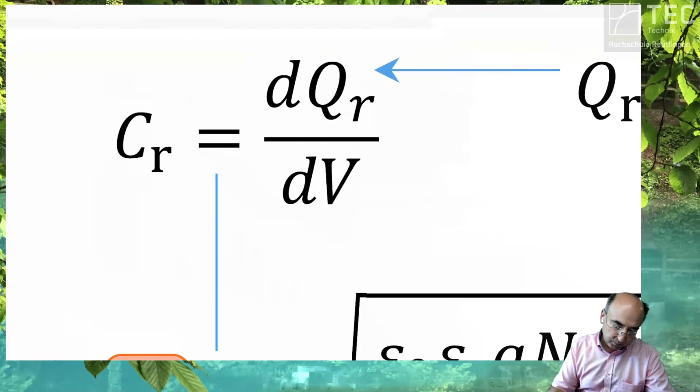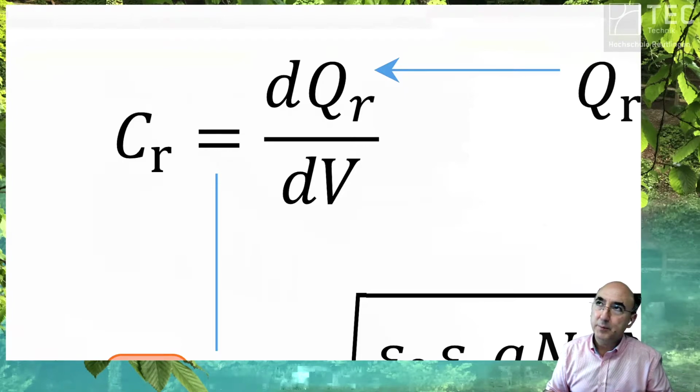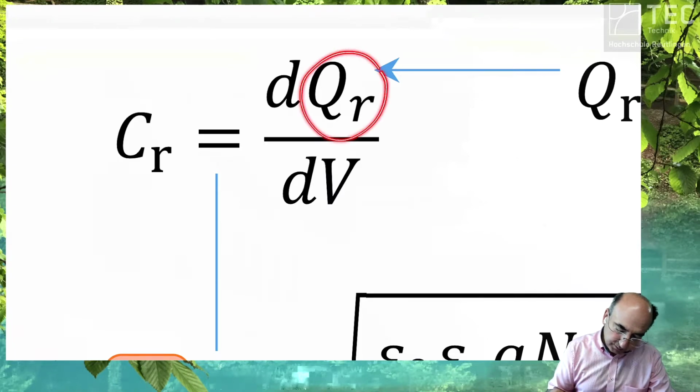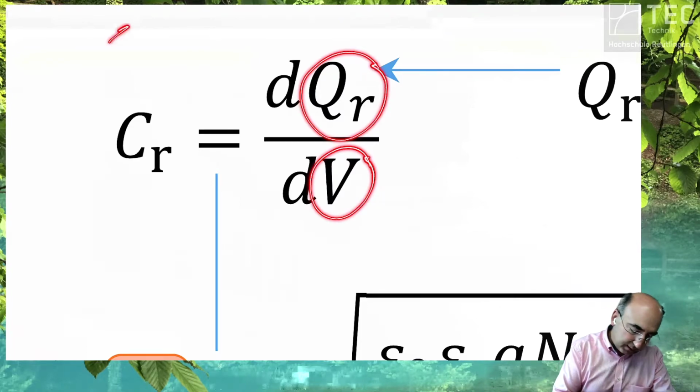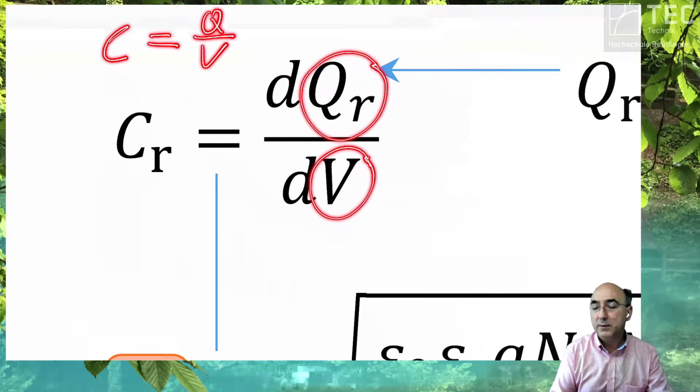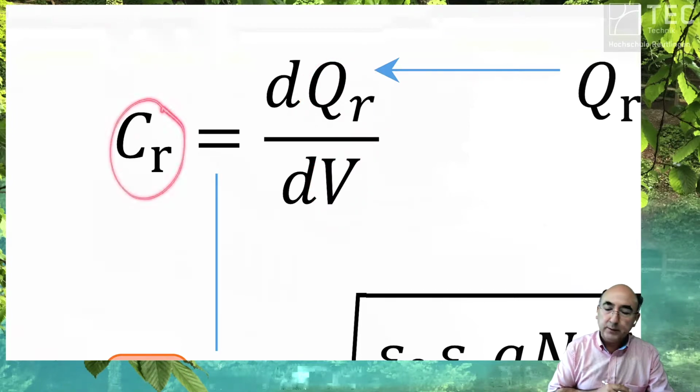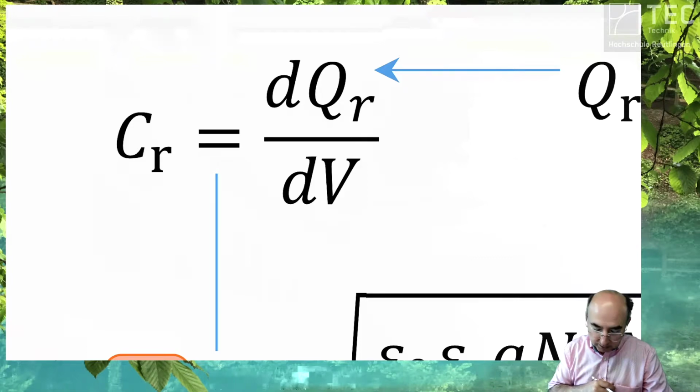If you define it by its small signal behavior, it's the change of the charge it stores by changing the voltage. If the capacitance is constant, then it is Q divided by the voltage. But here, as the capacitance does change, we take the derivative.